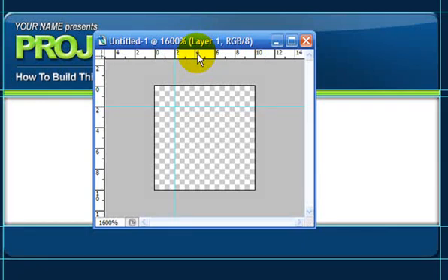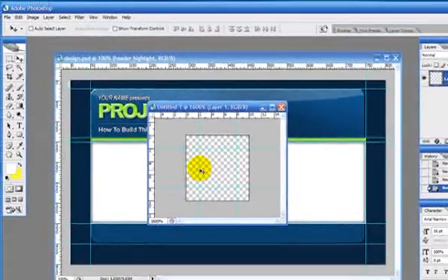Then I'll drag another one from the top. Now, knowing that this is a 10 pixel document, I need to drag that down to 8 pixels, so I have that 2 pixel gap still at the bottom. And then dragging one from the side, I'm going to put one over on the right hand side, again as we can see here at 8 pixels. So now I know that this gap around the outside of the guide square that I have is constantly 2 pixels.